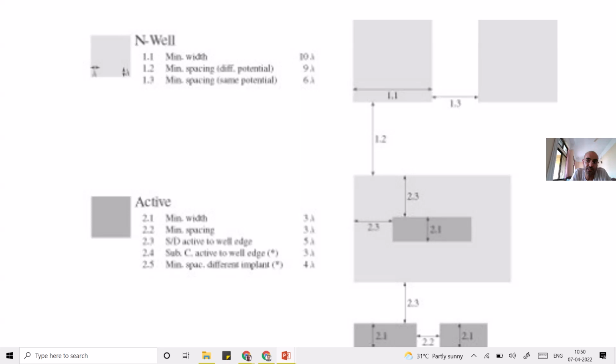The only engineering involved in defining these rules was deciding how much minimum distance the devices require to isolate them and avoid interference between them. All those calculations were done earlier. Once that was done by the fabrication laboratories, they give these rules to you. So whenever people are drawing the layout for these circuits, they have to obey these rules for a particular fab lab.